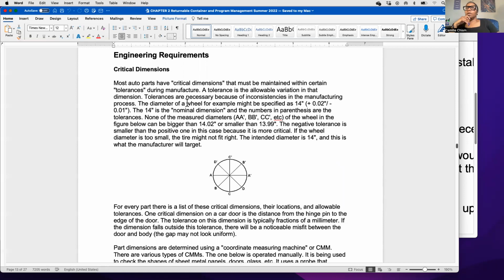So it's important to understand what the tolerances are for the parts, because if you receive a part and you design based on the part or prototype sample that you have, and you don't know what the tolerances are, you could say, I get this part and it's 1.25 inches, and you make the packaging design to fit 12 parts because you can fit 12 parts that are 1.25 inches.